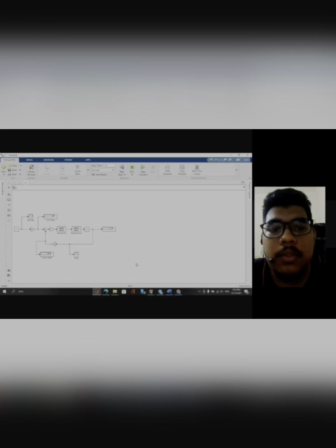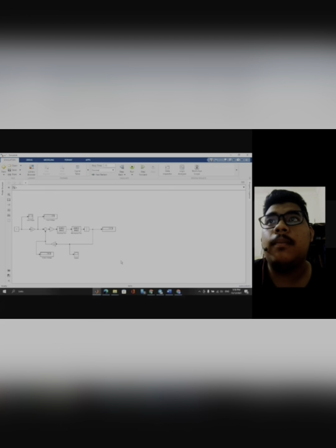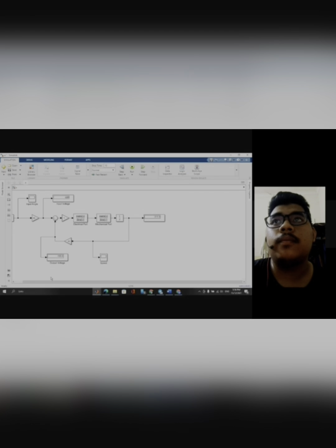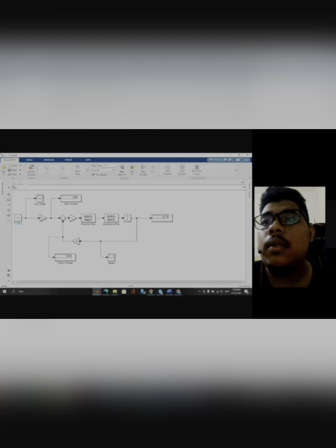Today I want to do a simulation about lab activity 2, that is closed loop. Now I show the simulation when the input angle is 5 and the attenuator is 1. I run the simulation. The value at input voltage, we get 3.056 volt. The shaft position is 3.927 position clockwise, and the output voltage is 2.4 volt.